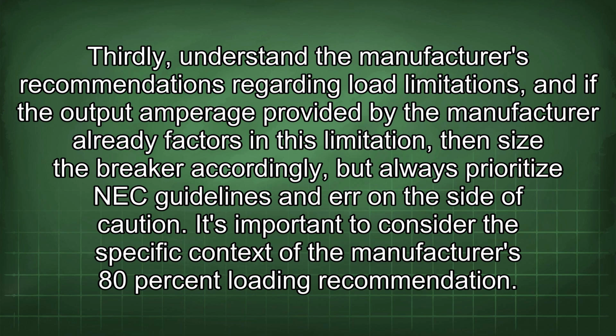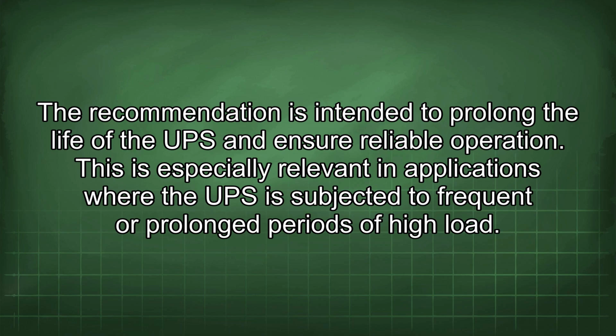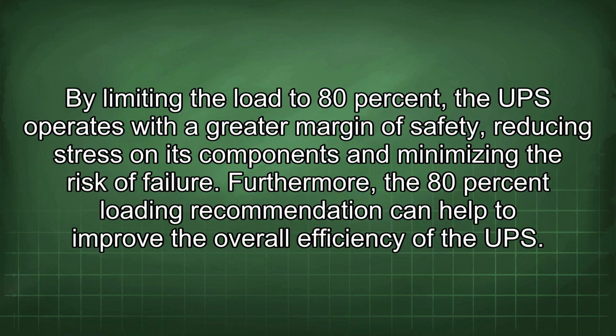It's important to consider the specific context of the manufacturer's 80% loading recommendation. The recommendation is intended to prolong the life of the UPS and ensure reliable operation. This is especially relevant in applications where the UPS is subjected to frequent or prolonged periods of high load. By limiting the load to 80%, the UPS operates with a greater margin of safety, reducing stress on its components and minimizing the risk of failure.